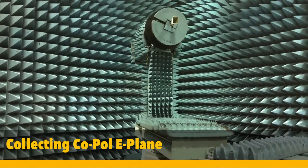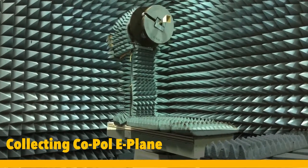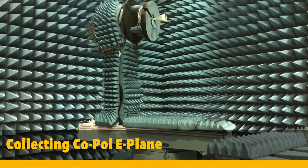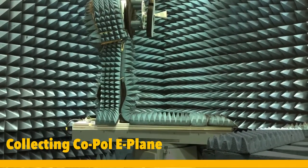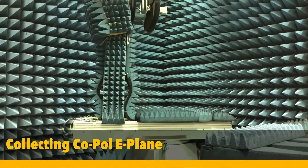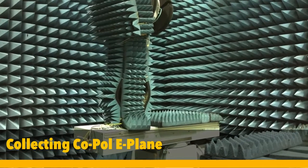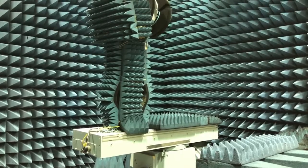Once we are done with the measurement, it's always good to check the E-plane cut copole with the H-plane cut copole to make sure that the peaks of these two cuts are on top of each other. If that's not the case, we need to check multiple things. One thing that you can always play with is the placement of the absorber in the anechoic chamber. Okay, now our measurement is done.